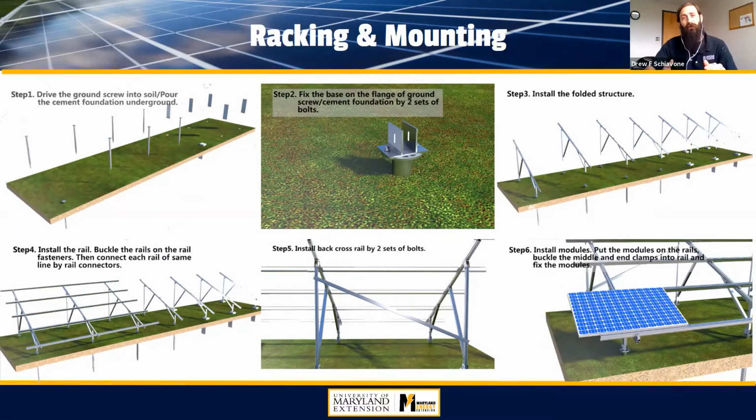In this case, you have a flange that sits on top of each pier. And you see that in step 2. That flange is nut and bolted onto the top. And then that flange is where the above ground structure fits in. And so in this case, they're using a folded structure. This particular model is highly adjustable to the tilt, but there's many options out there. I think in step 4, you'll see the railing going across left to right. There's a support beam on the back for more structural integrity. And then of course the modules sit down on the railing with those various clamps that are available.